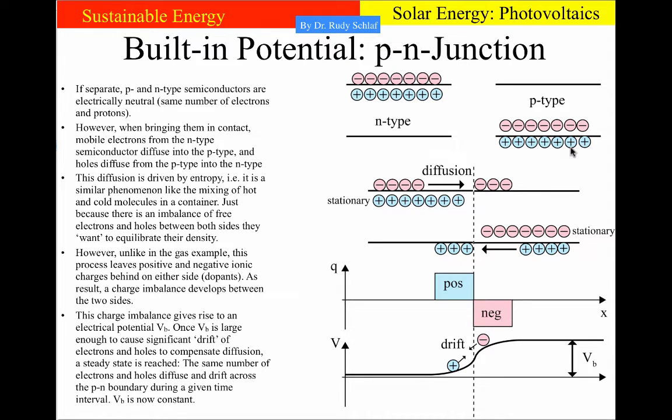So if we bring these two in contact, what happens is, because the electrons can move on the n-type side, they repulse each other, and that means they distribute across the entire slab of material, n and p-type regions. This means that on the n-type side we have some stationary positive charges that are not compensated by negative charges. They are now over here on the n-type side. Now with the p-type material the exact same happens, just in the opposite direction.